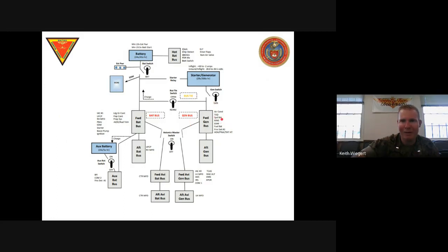You've got your trim aid device. That's that finicky thing that I told you about. Keeps the rudder in trim. You've got your speed brake. We've talked about the speed brake. Remember, no speed limit on the speed brake, but definitely get it in before you overspeed the aircraft to 316 knots. Your nose wheel steering gives us that left or right of center line, plus or minus 12 degrees. You've got your engine data manager. Again, your engine data manager is redundant on the generator side and the battery side because it's that important of a thing.